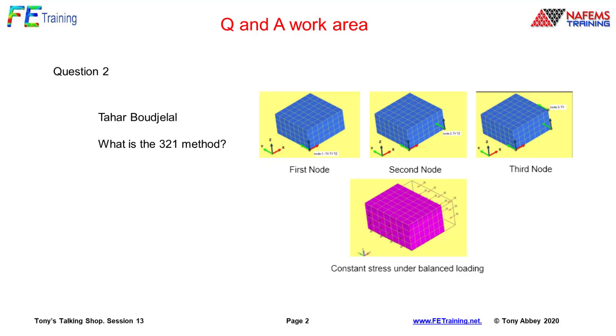It kind of goes ping. It goes into the shape it wants to go. To avoid that, there's a technique called minimum jig, or minimum fixture, which allows that component to expand, contract, whatever you're doing with fabrication. So when you take it out of that jig, there's no surprises. So it's analogous to that minimum jigging type of technique.